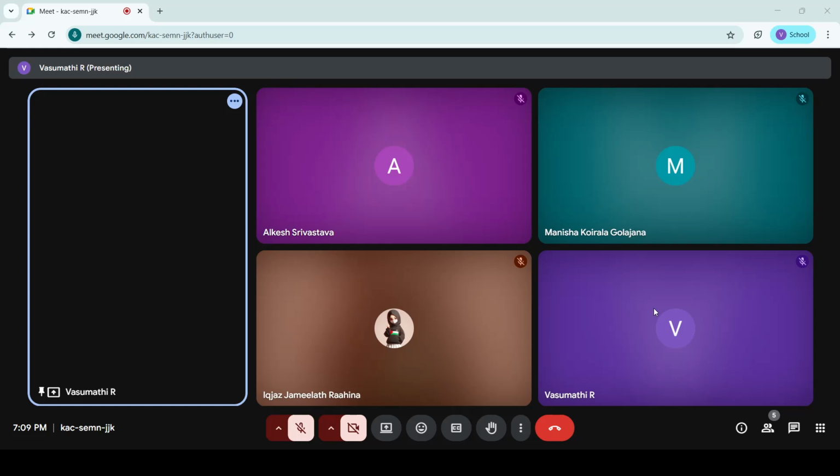Right? This will be output current equal to this term into input current. Here it will be output voltage in terms of input voltage. Okay, so we are going to apply the voltage divider rule here since our output and input are in terms of voltages. So that's why I have written it here.